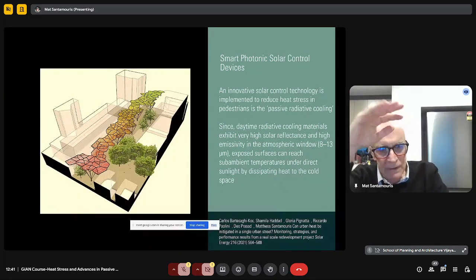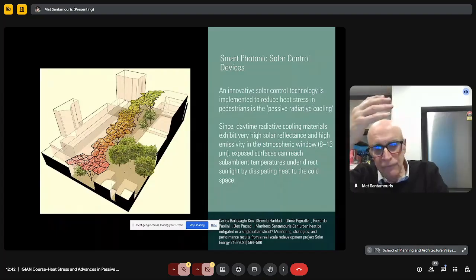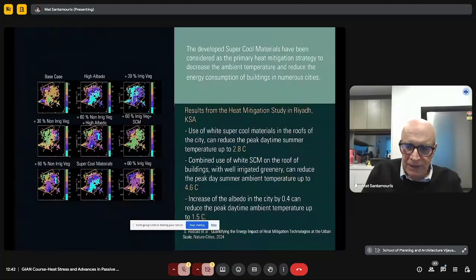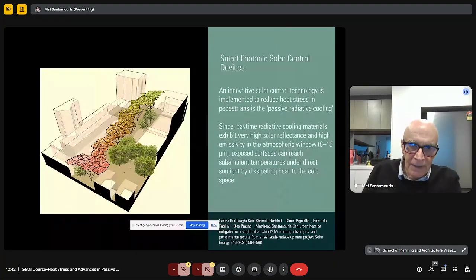These materials present a surface temperature 10 to 15 degrees below the ambient one. So once you are below this shading device, apart from the benefits of shading, you receive the coolness from these materials. So we provided comfort. We have not decreased the temperature further, but we increased comfort tremendously. This is a real project that succeeded in decreasing the temperature and improving comfort in the area by about 30 to 35%. And this is very important.